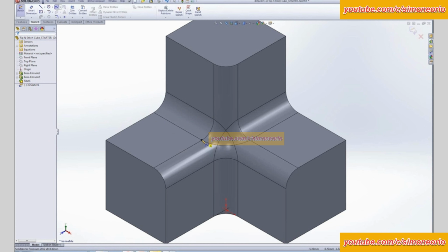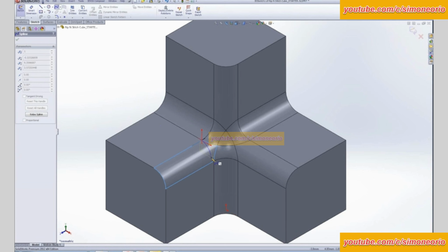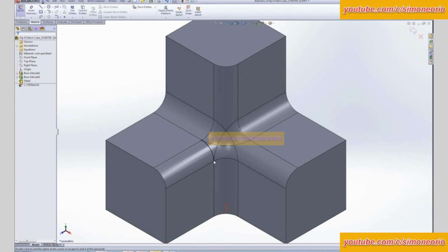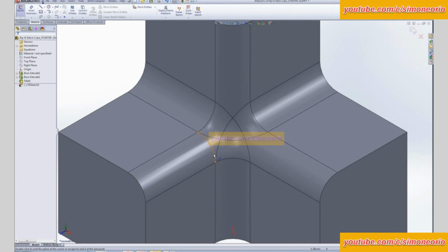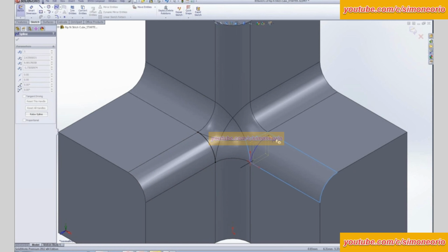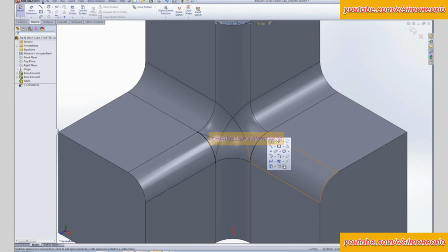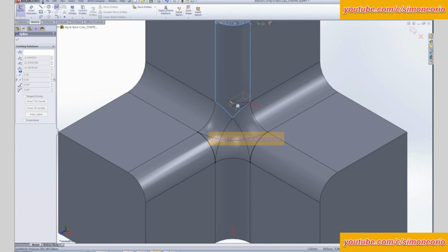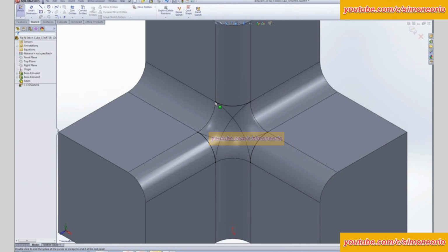And I'm just going to come to each one of these corners here, and I'm going to float over the surface that I want it on, strategically by the way, and then float down here to this other point, hit Escape to get on my point tool. Sometimes it's really easy to miss the points, and you might end up with a blue line, and if that's the case, you just kind of click and drag the endpoints of your curve there to get them to relate to where you want them to be. And so far we're pretty successful in not getting any underdefined blue geometry. You have to just be strategic with where you click and place your lines here.